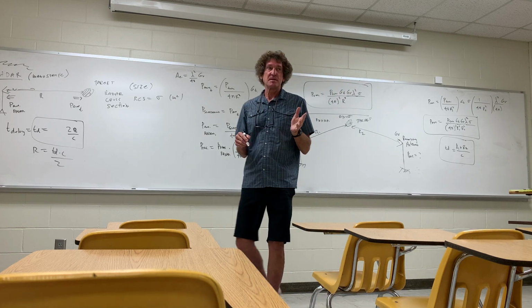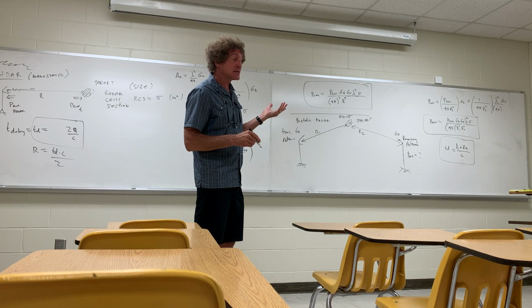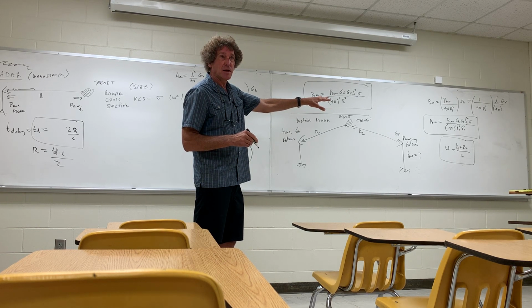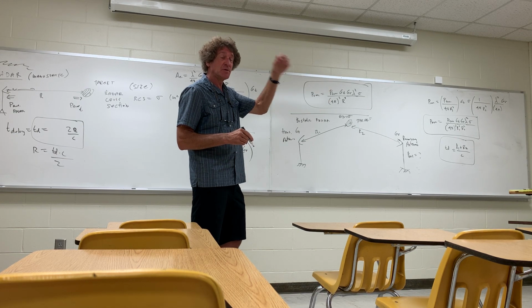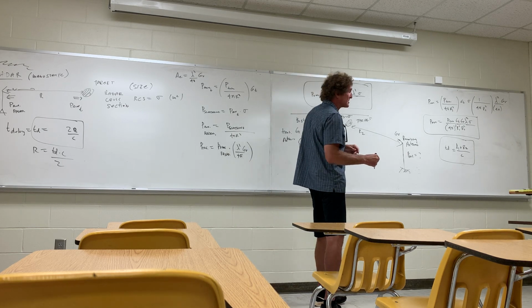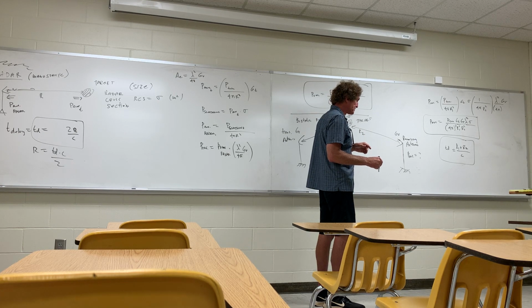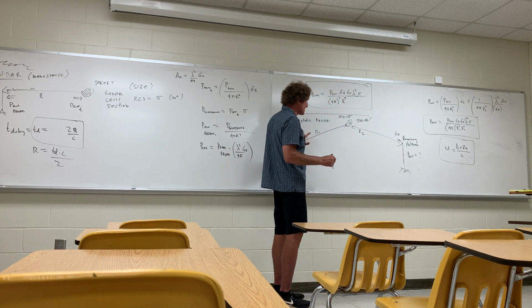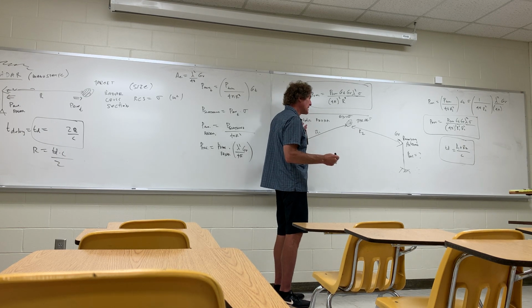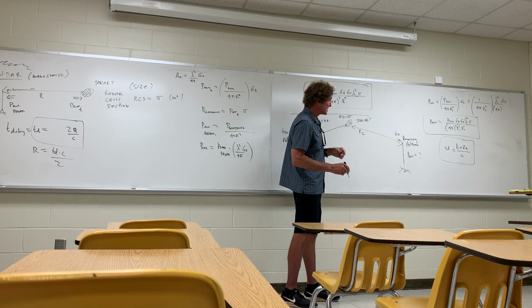Now here's the interesting thing with bistatic. You see how the time delay doesn't necessarily give you R1 or R2. Do you all follow me on that? You don't know which one it is, but the time delay is something that's actually available. The way they actually solve these things is, now this type of a target, is they have the aspect angles of these two things, where their peak gains are, and they can actually figure out, just by some basic trigonometry, where that target is. Okay.